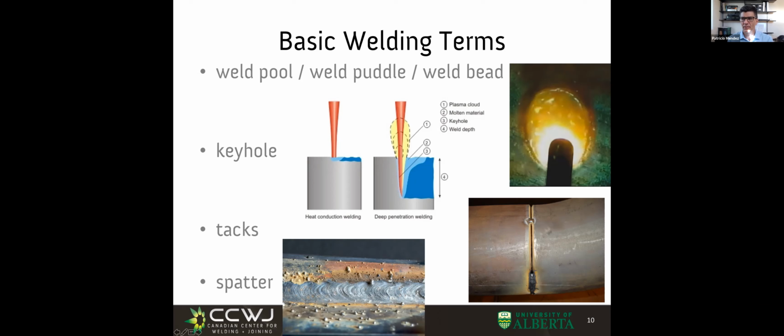And the reason I mentioned keyhole here is because when welders use electrode 6010, whatever it is, you're going to learn, it's a cellulosic electrode, but it has a very penetrating type of arc, and they tend to call it the keyhole. But it's a very different animal than this other keyhole for electron beam welding. So I just wanted to introduce the term, and we'll get deeper into that later on.